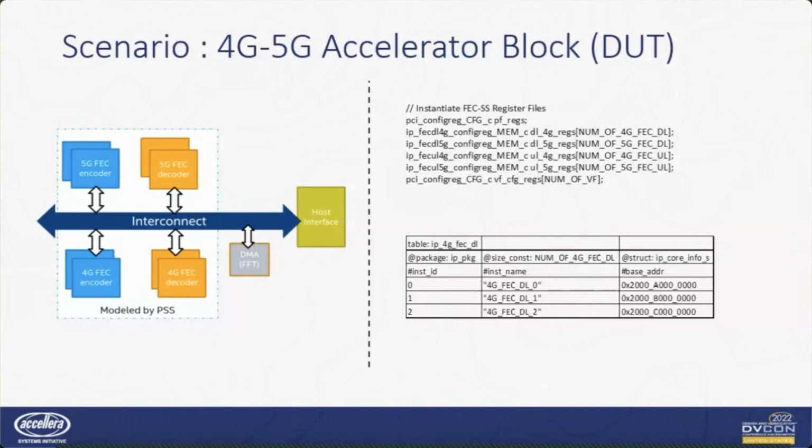The CPU receives data over the radio network and it writes this data into memory. The CPU then writes a descriptor into memory which contains addresses of input data blocks and addresses of blocks for output data. The descriptor address is then written into queues which are present within the IP, and the DMA engines present in the IP fetch the input data, and they also write the output data back into the memory once the FEC blocks are done processing data.